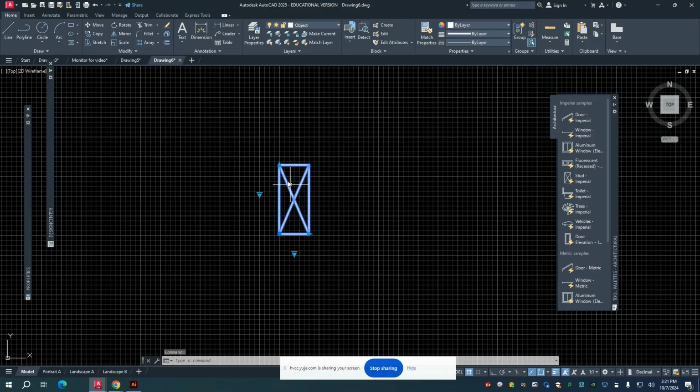And you'll notice that it has a couple of grips. So it's got the triangle grip up here, another triangle grip here, and it's got triangles on the side and below it. They each have slightly different purposes, but basically do the same thing, meaning the side grip here, the triangle, I click on that and I can change this from a 2x4 to a 2x6 or to a 2x8. And it's all programmed in there.